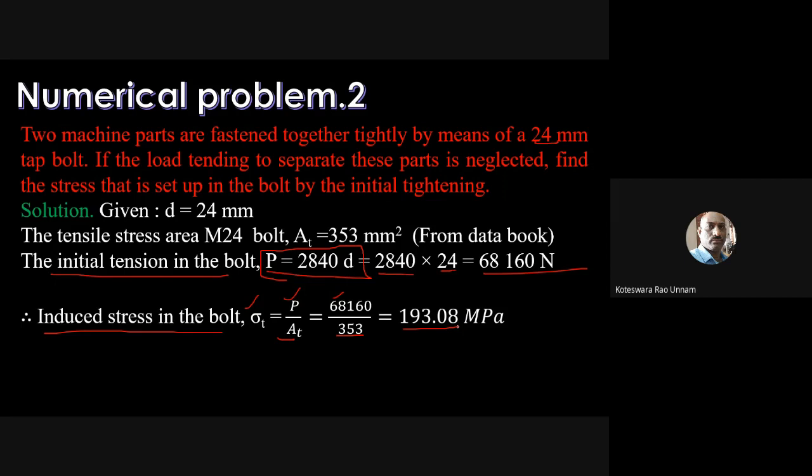So since the bolt having 16 mm or less than 16 mm is failing because of initial tightening, you cannot use these bolts for fluid tight joints. Like that you can prove it. So without giving numerical values also, they may frame the question something like that. But like I already told in the previous class, you have a data book with you, you need to collect all the data pertaining to that particular problem and you need to solve the problem.